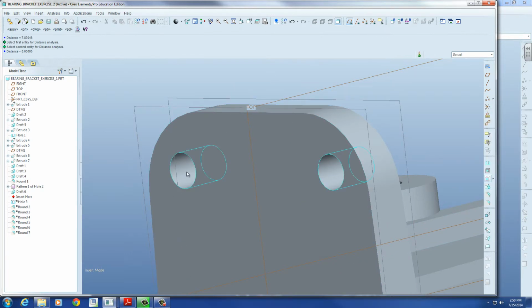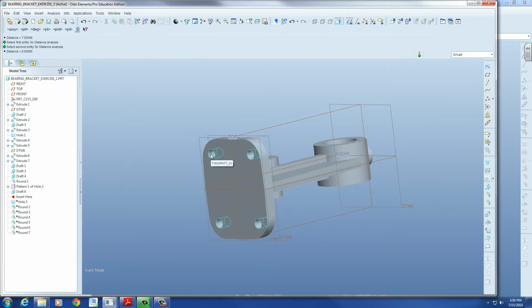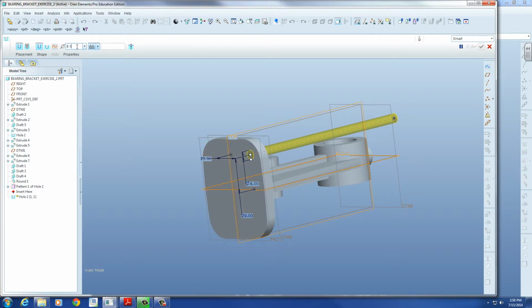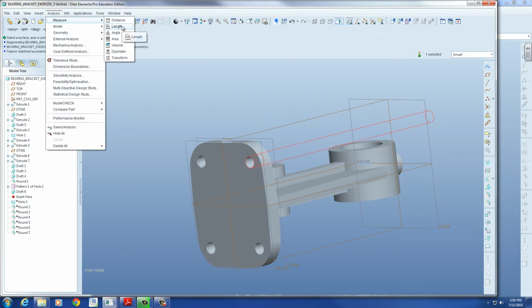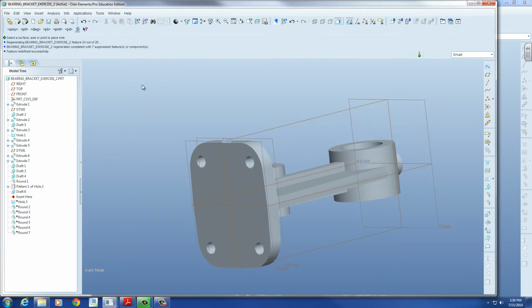So we would go back and change the diameter by the difference in these two things, which would be 1/10 of a millimeter, 4 thousandth. Right? So that'd be 8.1, right? All right, so where are these holes? If I edit the definition, but doesn't that accomplish the same thing as making it bigger at the bottom anyway? Inching it from the top of the hole to the bottom. I thought we were doing that already and it wasn't doing what we wanted though. We were maintaining aspect ratio at the bottom and then made the top smaller.